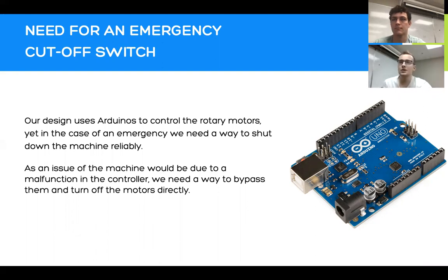In designing the emergency cutoff switch, we needed to keep the switch in line with the power supply and motors. This was so that in the event of an emergency, we could immediately kill the motor's power rather than turning off the power supply, as this would cause a time delay and the motors would continue to receive power for up to 5 seconds. By adding the emergency cutoff switch, we can allow the user to more immediately kill power should the need arise. However, the act of using a mechanical switch raises a new problem for a more immediate shutoff of the Stewart platform, which is switch bounce.